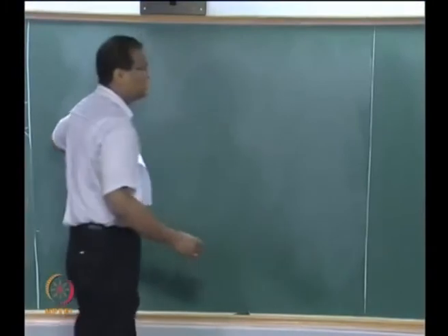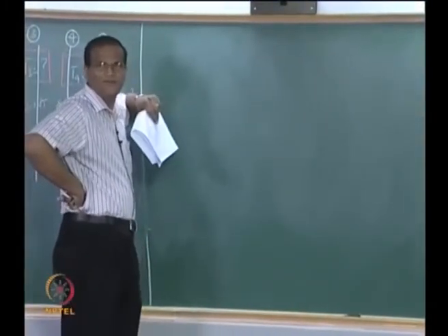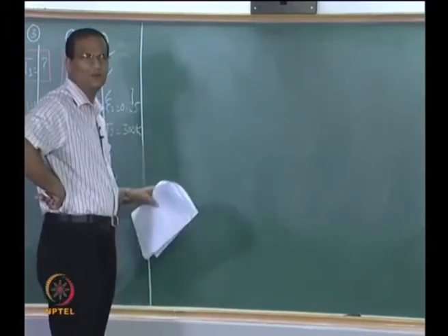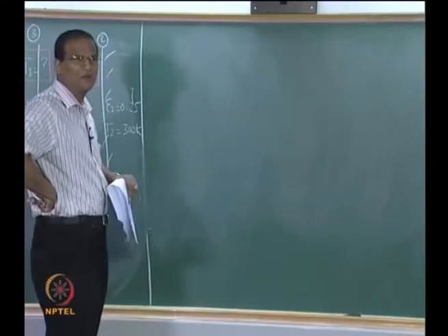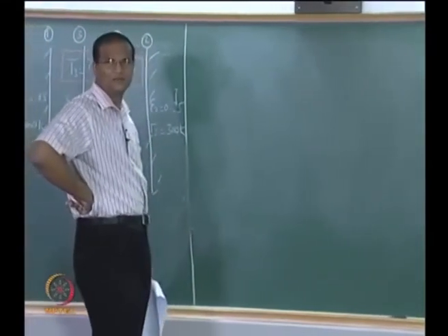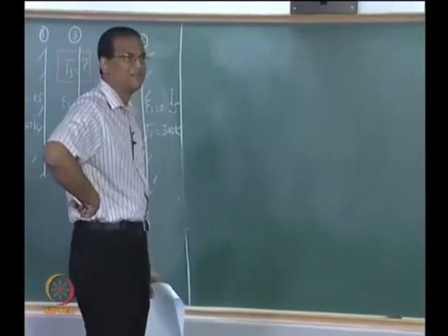The other way of checking is T3 and T4 must be between T1 and T2. Otherwise you are in trouble. There is no heat generation in the problem. Heat is flowing from left to right. So from left to right the temperatures have to continuously decrease. These are what are called common sense checks.